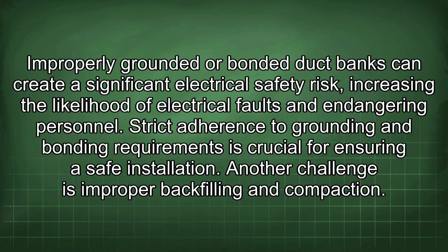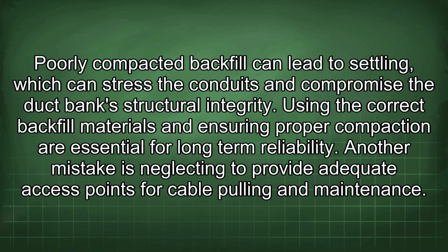Another challenge is improper backfilling and compaction. Poorly compacted backfill can lead to settling, which can stress the conduits and compromise the duct bank's structural integrity. Using the correct backfill materials and ensuring proper compaction are essential for long-term reliability.